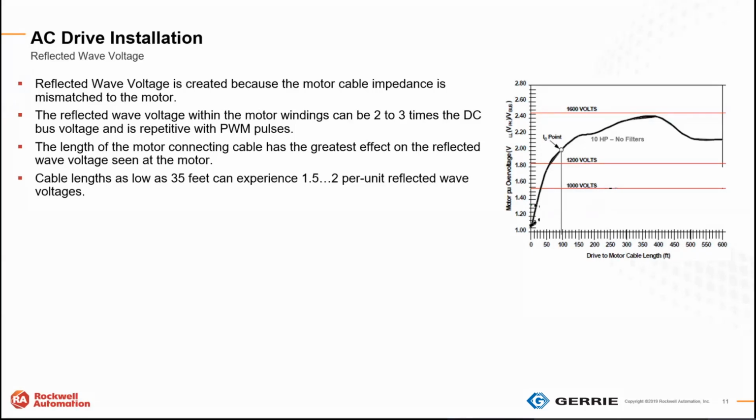Then the other phenomenon that we have is the reflected wave, which is caused because the high frequency surge impedance of the cable doesn't match the motor surge impedance. I was talking about that before. So why don't we just try to match the impedances? Well, it's really not practical to match it, so we need to deal with the issue.